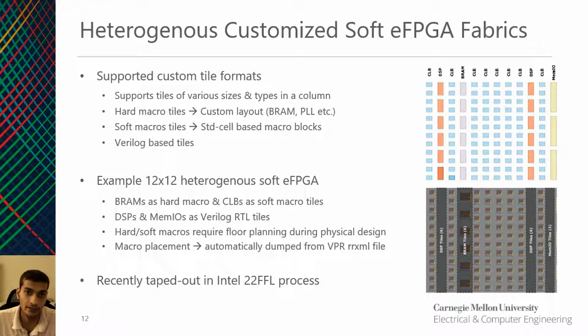Hard micro tiles are supported for including logic blocks with custom layouts such as BRAMs, PLLs, etc. Soft micro tiles are supported for including macro blocks that are built using standard cells, and we also support tiles that are described in Verilog.